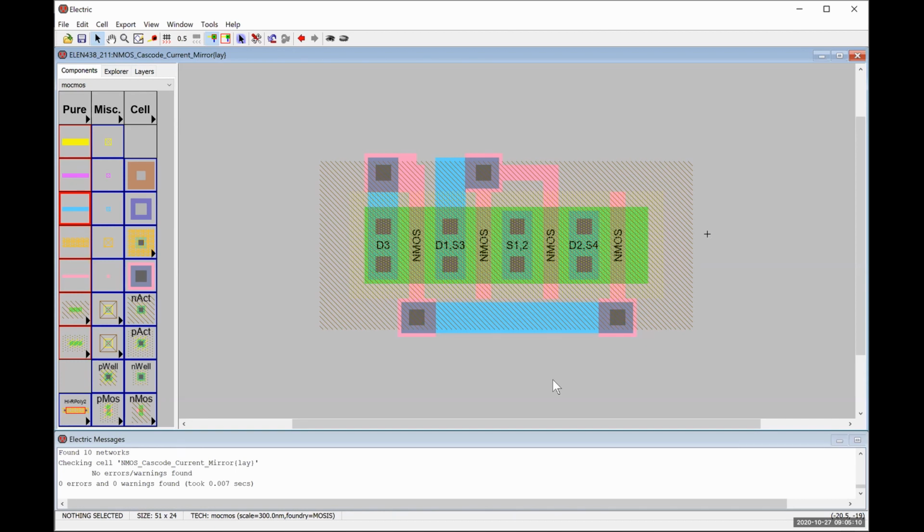So why did I choose to use metal over polysilicon there? So you could run the other ones under it. Well, but that gate connection down at the bottom transistor on transistors M1 and M2 aren't going to go under it, although that would be a good reason to do it. I'm doing it purely because it's way less resistive than the polysilicon, right?